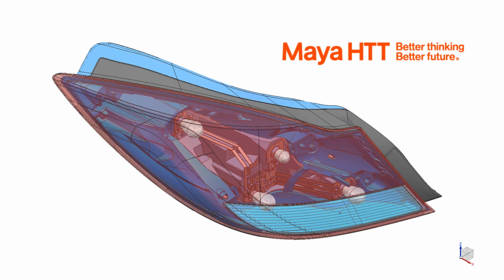In solving thermal radiation models, the most computationally expensive portion is the view factor calculation. One method to reduce this computational time is to explicitly define the radiation enclosures.